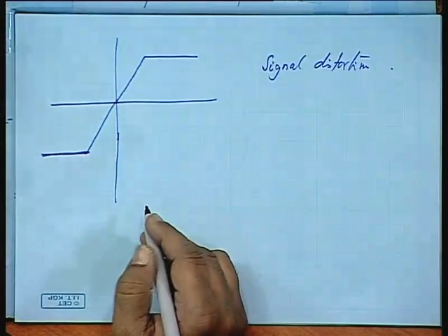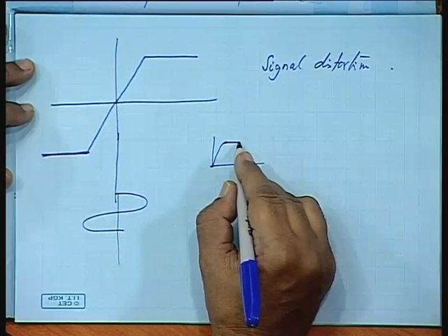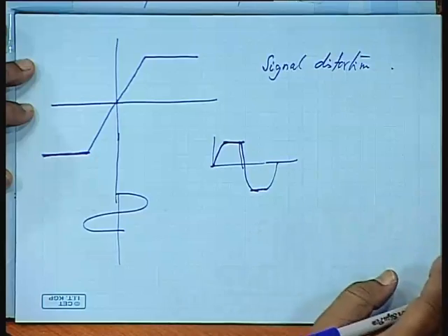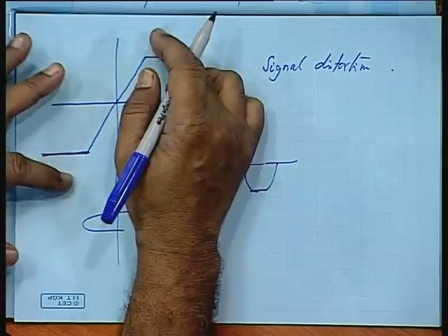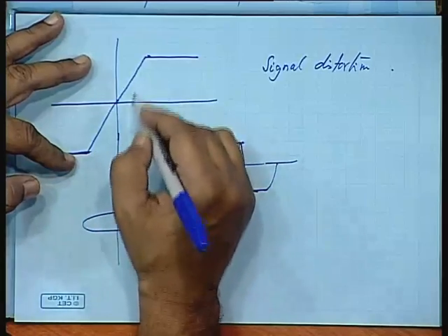You have seen nonlinearities of this kind, for example, in an analog signal, if you feed a sinusoid, what will be the corresponding output? It is clipped here, is it not? So, there is a distortion. So, what is the remedy? We try to reduce the magnitude. You multiply by a scaling factor, so that it oscillates within this limit. The variation takes place only within this. So, whenever you are designing a digital filter, you have to see that for a given input at any intermediate stage, the overall output should be restricted within this range. So, we should have a scaling factor, a multiplier, to control the input such that at any intermediate point the output should not exceed +1 or -1.